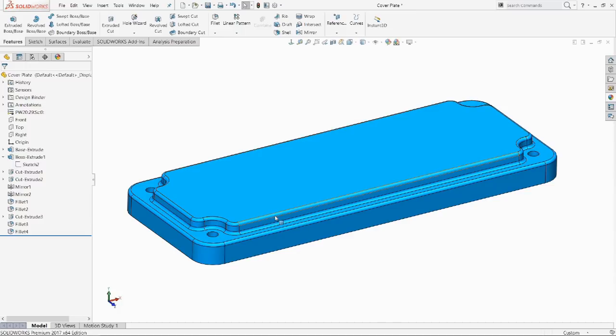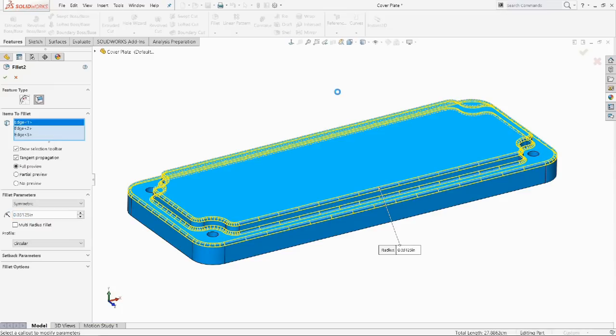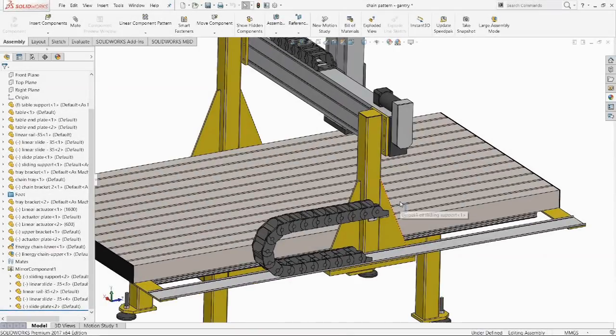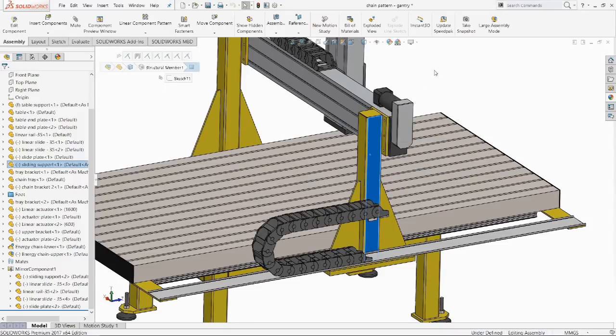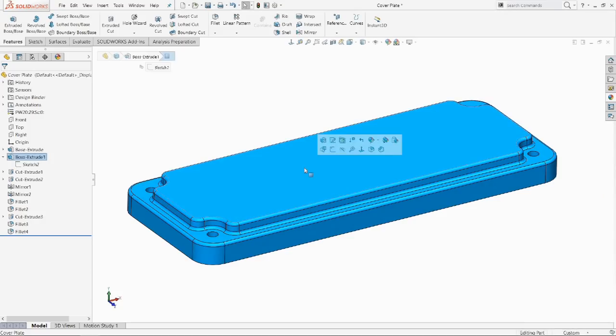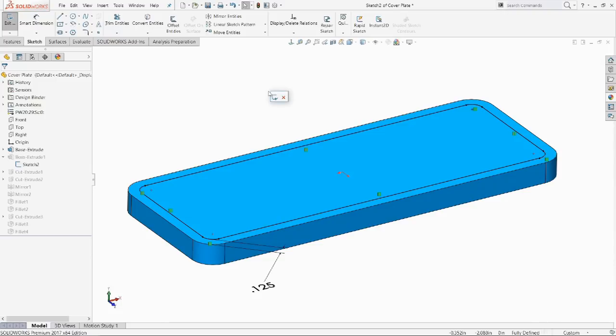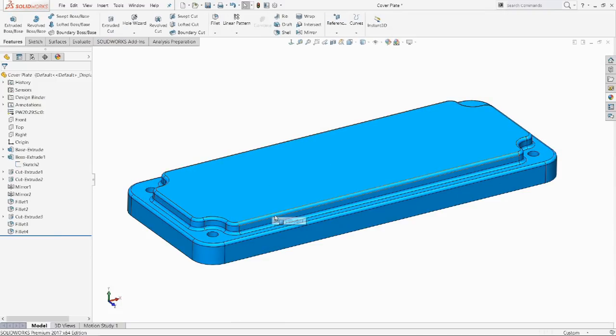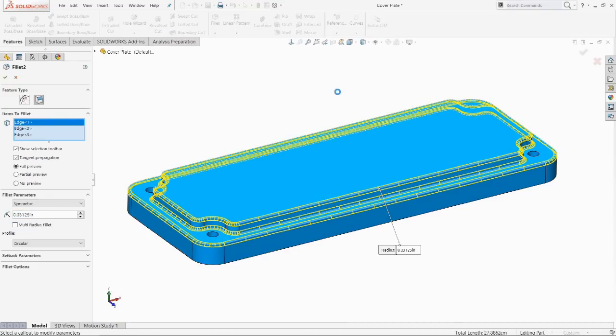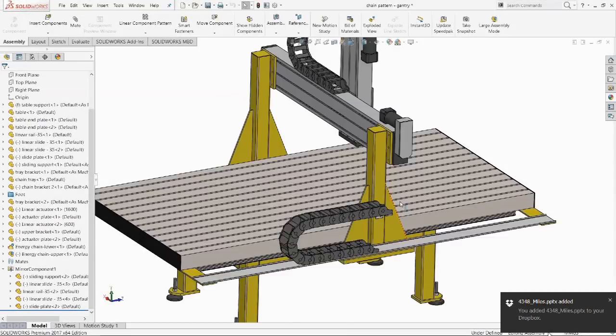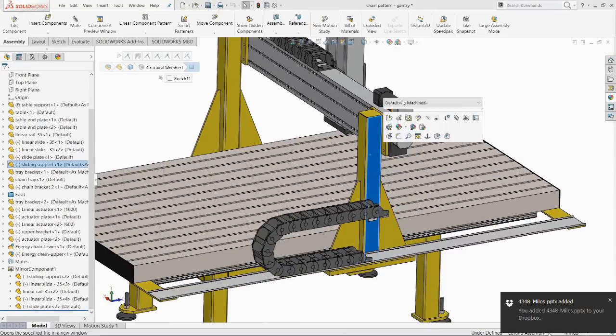And you hit D again whenever the confirmation corner is active, like the check mark and the red X for cancel, and it moves it right to your mouse. So it's not that groundbreaking of an enhancement, but really breadcrumbs is pretty great. It was added last year to the software. Essentially, it offers you all of the things that you would ever want to find from your feature tree by just clicking on the entity in the screen. So you click on a face, it brings up that sketch, the feature, the part, the body, the assemblies, all the mates. You can access everything directly, graphically, by clicking on it that you would from the feature tree. So you could essentially model with your feature tree collapsed. That's the way I like to look at it.